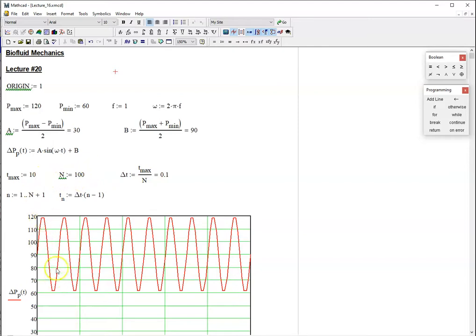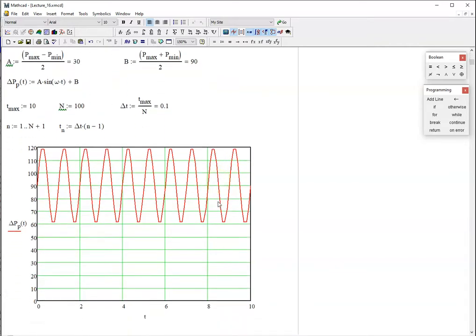As you can see, the pump pressure is very choppy. And if you remember from lecture 19, when we try to use this with a standard Runge-Kutta approximation, we got nothing. We actually got the solution to blow up, to go to infinity, as these errors propagated. This instability induced by the valve actually caused instabilities that made the numerical error be large, and then propagate in time, and then give you meaningless solutions.